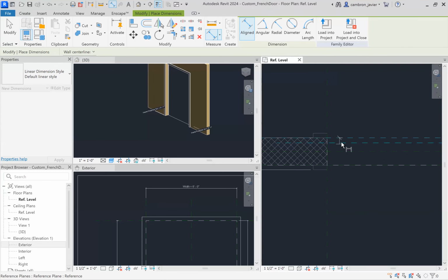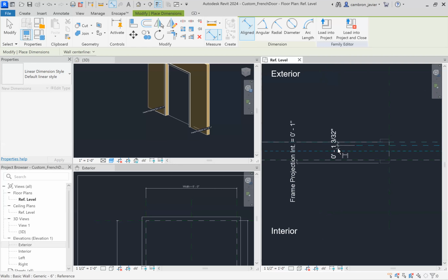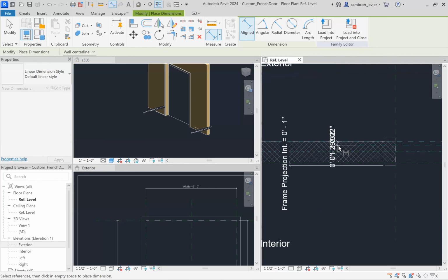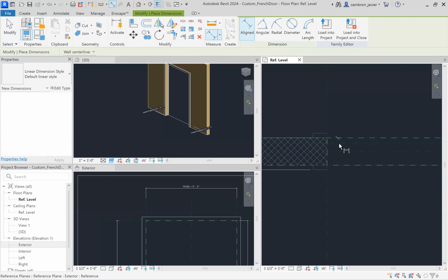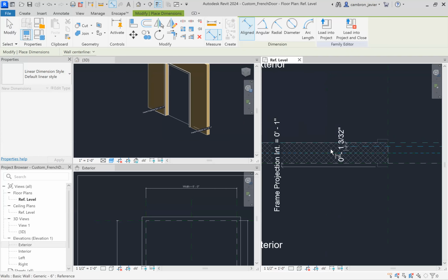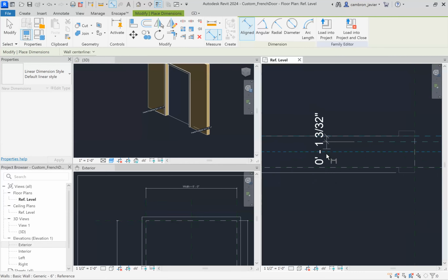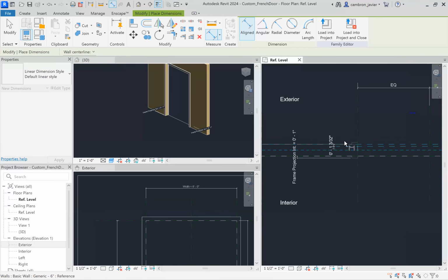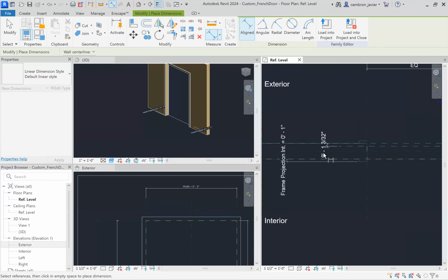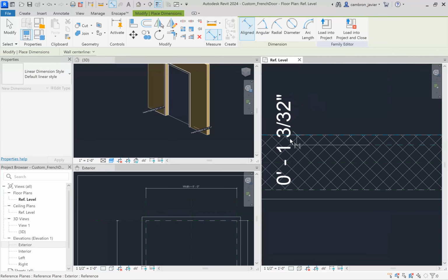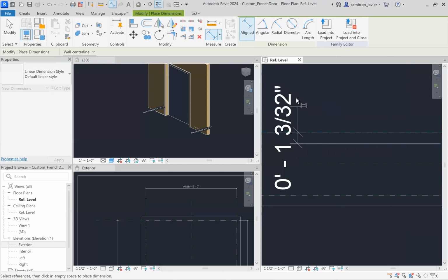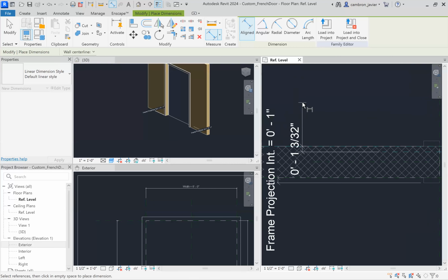So I'm going to click there, and bring this out. Oops, do that again. This gets a little tricky, so let's click there. This is one of the things that happens when you start to have more and more objects or items there to select. Revit wants to dimension to everything. So let's pull this out, and it's actually better to zoom in and move the cursor away where there's definitely nothing out there.